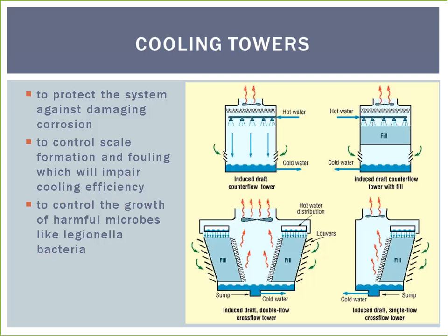As a general rule, the more scale forming a water becomes, the less corrosive it tends to be to steel. This means that provided scale formation can be effectively inhibited, it is beneficial to operate a cooling system at an elevated concentration factor. Therefore, close control of the cycles of concentration is critical to cooling water corrosion control. In effect, you are making the water chemistry work for you rather than having to fight against it.